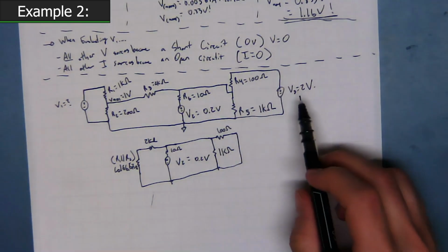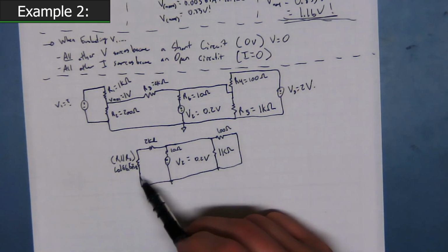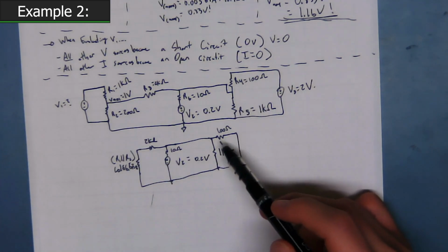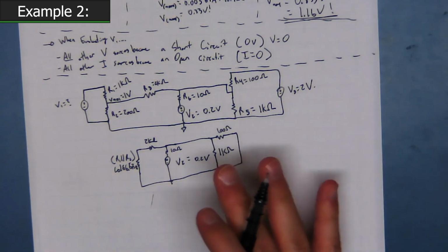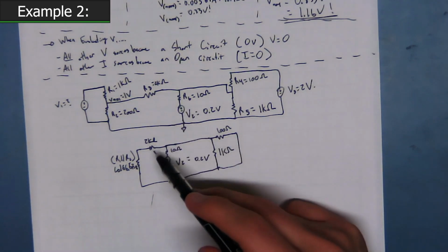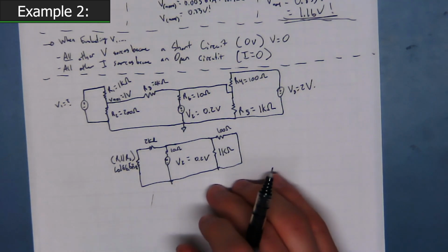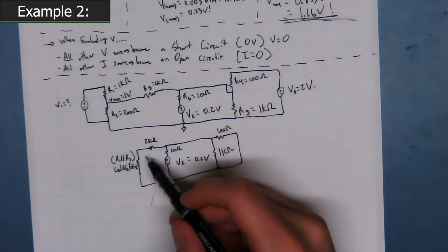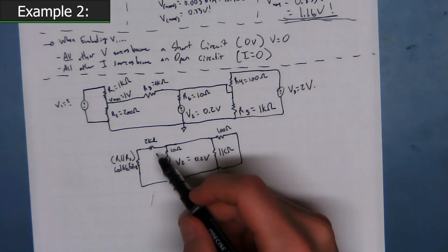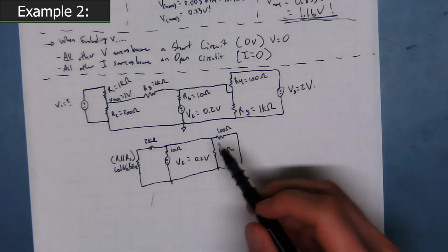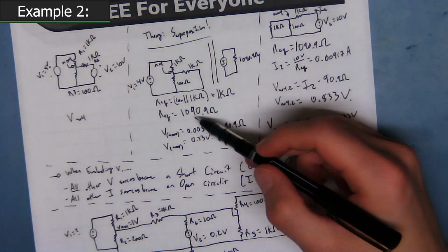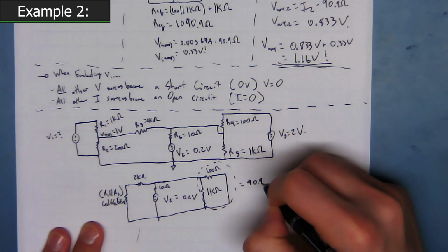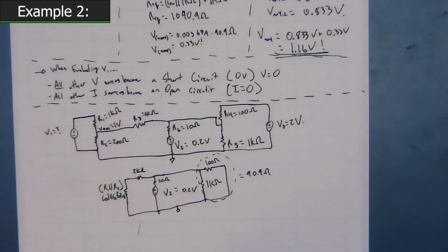So just to show you what I've got here, right? V3 is represented as a 0 volt source. V1 is represented as a 0 volt source. We've put those two in parallel to build this network. These two are now in parallel to build that network. I drew it a little differently. I combined one of them. I should be more consistent. Sorry about that. So then we've got R6, R3. Everything else that has not been combined still appears here. Okay, so we're going to call that 2,166 ohms. We're going to combine those two in series. And then we have this parallel combination of 100 and 1K. And if you remember back to our previous problem, we already solved this. We know that that is 90.9 ohms. Okay, so I'm going to come down here and say that is equal to 90.9 ohms. And never forget your ground reference. It's very important.